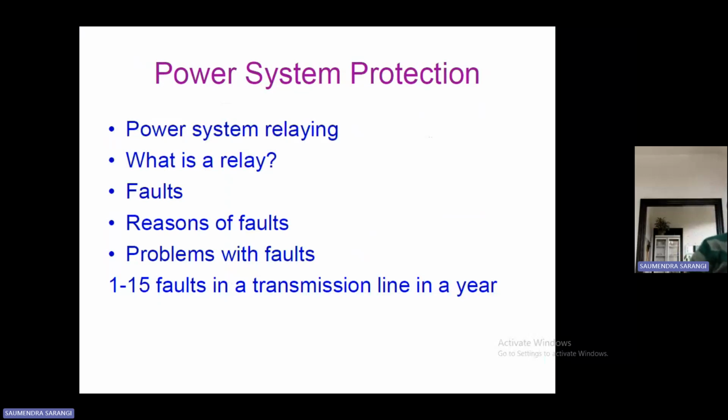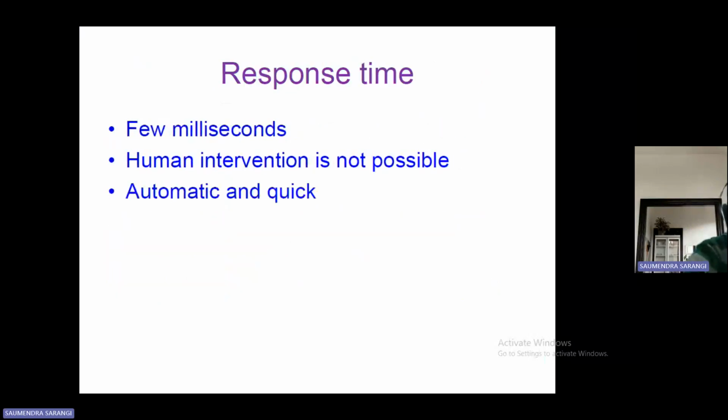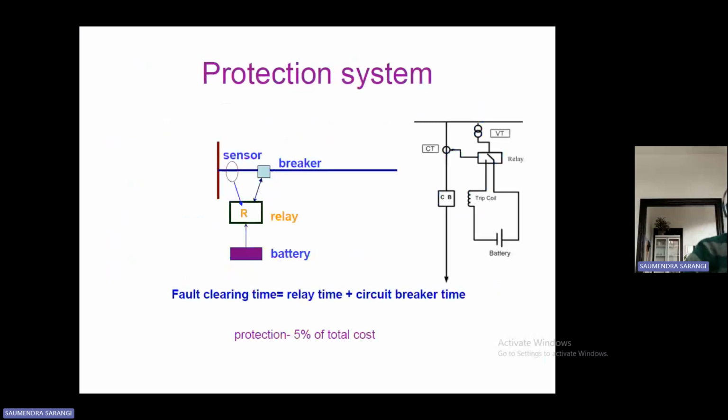But when you understand the shunt faults, they are the severe faults. In the open conductor fault, when suddenly there is an open circuit, the power cannot be transferred. The voltage may go a little bit high because of the open conductor fault. So now we have understood the relays here, that is how the relay is getting operated.